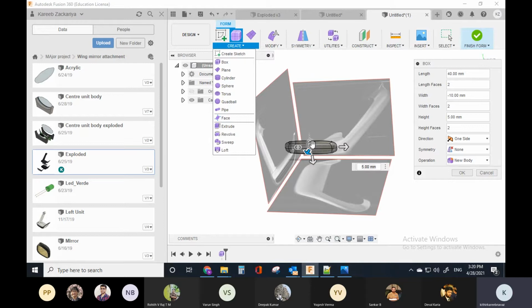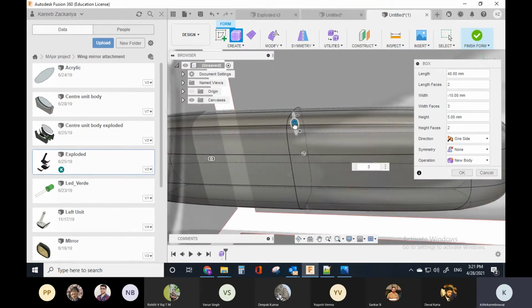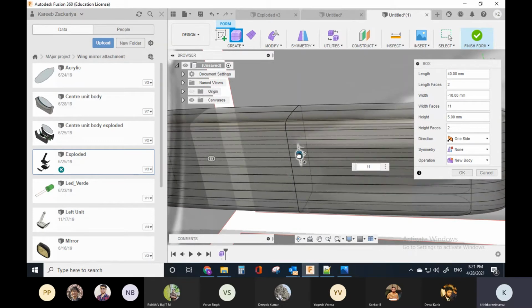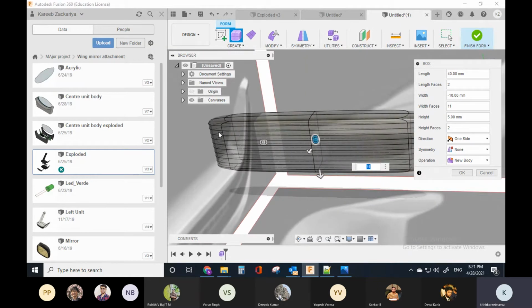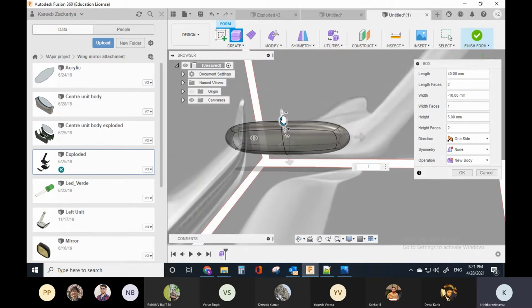This handle defines how many T-spline curves you want. So there is only one T-spline curve on this box. If you want more, they get increased. You can do as much as you want and control it whatever way you want. My personal advice is, you keep it as low as possible and use it wisely. You should keep as few T-spline curves as possible, only for the features that you need.